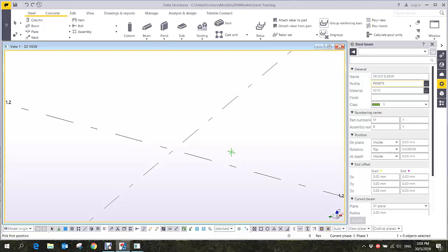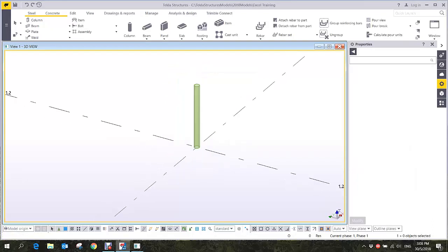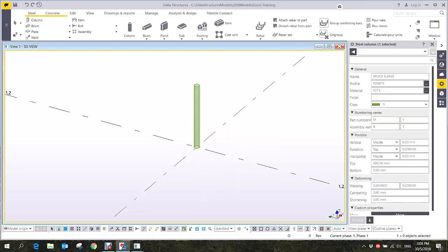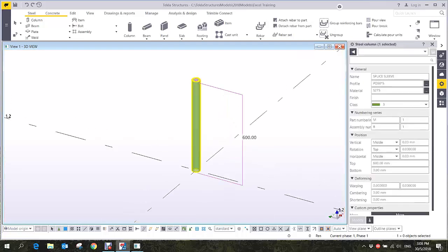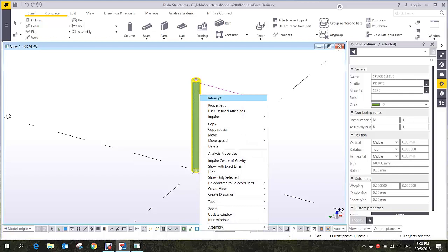Okay. So click 1 and then 600, right? 600. There you go. So in this case, you can right click, you can create the 3D views of the part. So you can isolate the 3D view or default views of the part. So it means it will create 4 views. The top view, the side view, the front view, and then the 3D view.